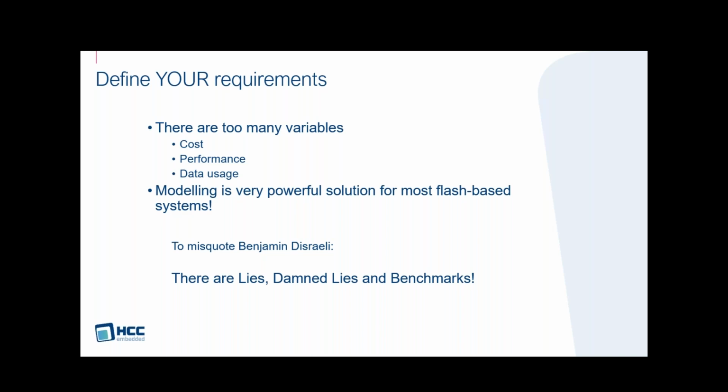I have one very educational benchmark that HCC generated many years ago on an MSP430, where we managed to create relatively fast writes to an SD card, writing data from RAM using DMA. I think it was on an 8 megahertz processor, maybe getting 50 kilobytes per second, which is quite a low speed by today's microcontroller standards, but for that time was actually good performance. But it would only run if you could do continuous DMA.